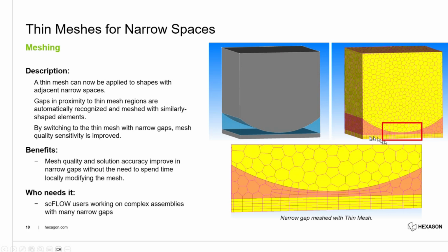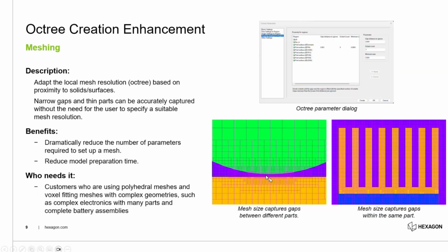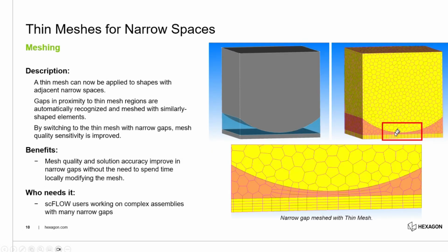So again, let's say the aileron and the wing will probably be closer to something like that maybe. But the problem is if I refine the mesh using the previous approach, this means I'll have smaller elements in two directions. But what we typically find is that the region there starts to utterly dominate the mesh in terms of number of elements. That finer mesh requires finer mesh there than I would have needed, which in turn needs finer elements there. But it's not just in one direction, it's in all three directions. So if I take a hex element and I halve it in all three directions, I end up with 8 times as many elements. And that's not the only problem.